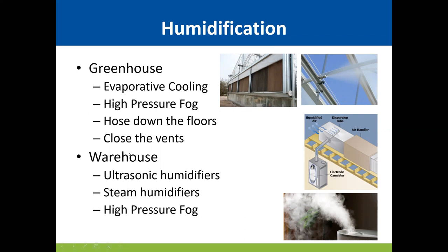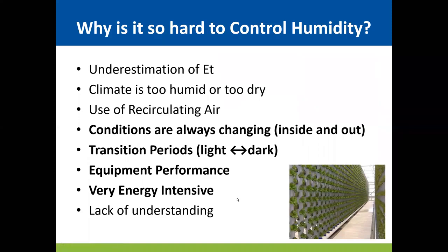With a warehouse, we tend to do things a little bit smaller scale or a little bit more gently, I would say, using ultrasonic humidifiers, steam humidifiers that can even be placed in the air handling, air conditioning equipment. And some people do use high pressure fog, say in their clone rooms.